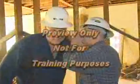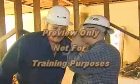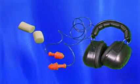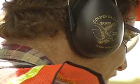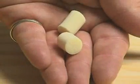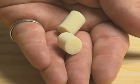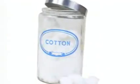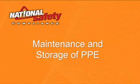If you cannot hear a fellow employee in an area without shouting, then you probably need to be wearing hearing protection in that area. Ear muffs, ear plugs, and canal caps are some examples of hearing protection. Earmuffs fit over both ears and reduce noise 15 to 30 decibels depending on how they are manufactured and fit. Earplugs are inserted into the ear and completely block the canal. Earplugs reduce the noise 15 to 30 decibels depending on manufacture and fit. Cotton is not considered an acceptable hearing protection device.